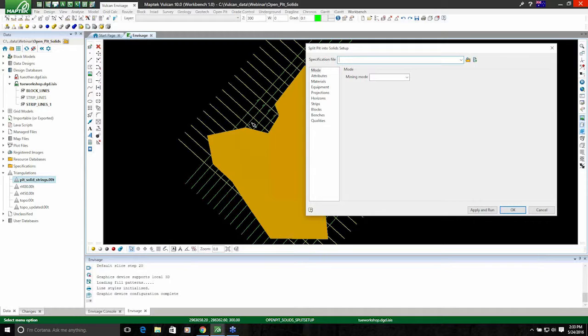We also need some strip lines, so they can be either 2D strip lines, as I'm using today, can also be a benching and battered projected strip line, or you can also use triangulation templates, which you've created by manually projecting your own strips through your horizons, or adding in ramps, however you want to go about doing it, triangulating your strips, and we can add those in.